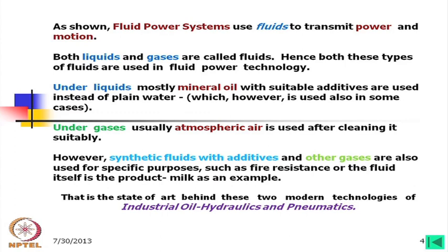Now, here I would like to mention, in hydraulics the fluid which is used is considered as incompressible, whereas in pneumatics, be it air or gas, this is compressible. So, definitely the behavior will be different, and we have to go for separate analysis for these fluids.